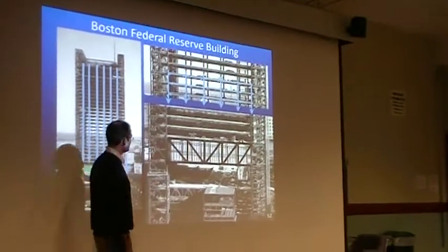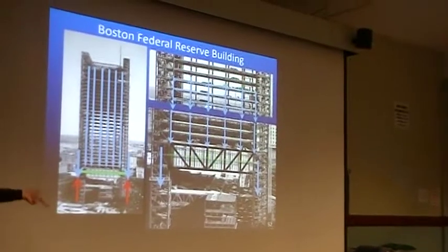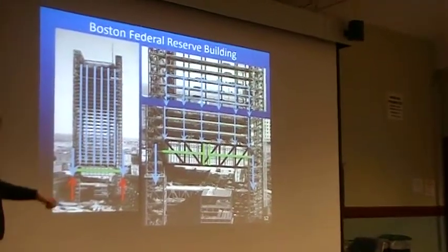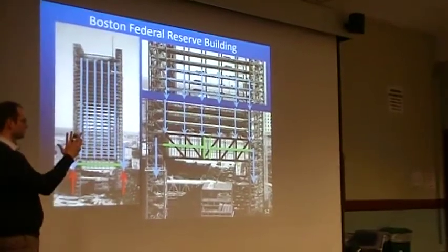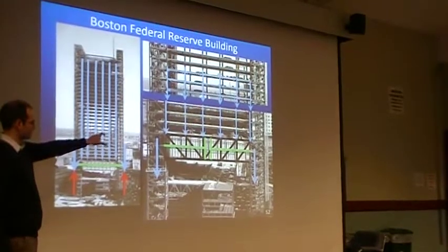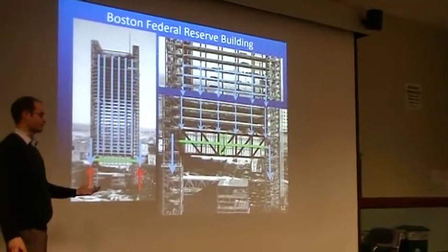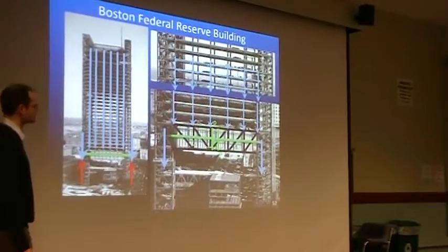But he needs to do that to get the dead load over the sides to resist the uplift forces. Oh, and by the way, if you wanted to design the truss really quick, you could put 2 cantilevers back to back, treat it like a beam, and you can get the pushing and pulling forces of the top chord and bottom chord really quick. Just trying to show, if you get that in your head, no structure can't happen.